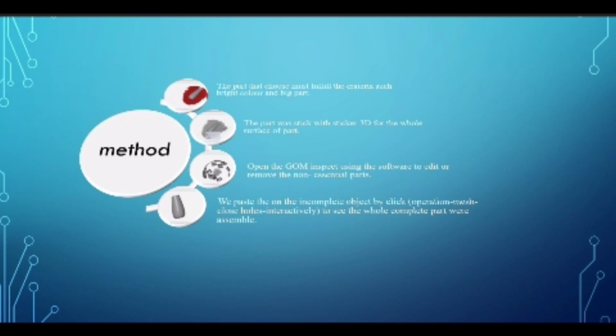The result can be seen in GOM Inspect. We need to open the software GOM Inspect to edit or remove the non-essential parts. After finishing removing the non-essential parts, we patch the incomplete object by clicking Operation, Mesh, Close Holes interactively to get the whole complete part assembled.